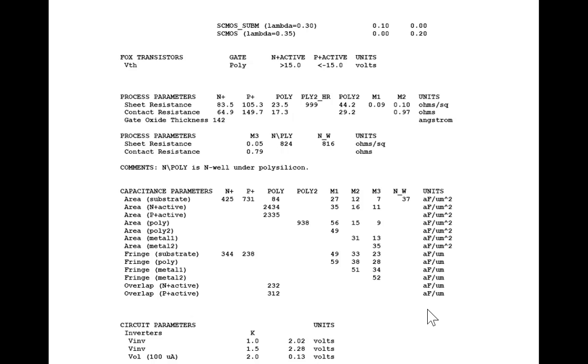So this is the capacitance per unit area of the gate. Remember we said the oxide underneath the gate was real thin? If the oxide is real thin, it has a high capacitance density. So we see a real high capacitance density from poly to substrate. That's COX. We're going to call that COX later.